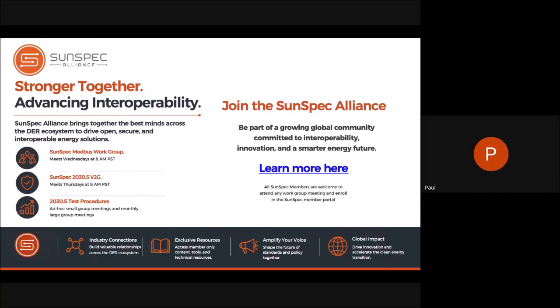Where I'm trying to picture, and admittedly I have a narrow view of residential hybrid, what we call hybrid inverters. You're right, hybrid's probably a bad term. And I'm trying to understand where the communications would be going to and from for this. That's relatively easy. I'll explain that one. I actually give presentations on this stuff all the time. So your prime inverter is in a communications network, period. It has data packets that are transmitted over, for example, SunSpec Modbus. Or it could be an RS-485 communications daisy chain system, whichever.